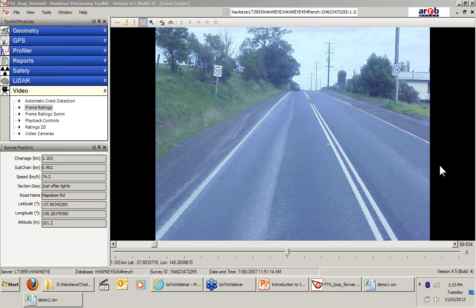We do have a sensor which these customers can use, which is like an infrared switch. So if you want very, very accurate referencing, you can put bollards on the side of the road, and when the front of the vehicle goes past it, a reference point can be entered. But typically, when a normal operator enters reference points, they can be around 5 to 10 meters off, and some adjustments may be needed within the processing software to fix that up.